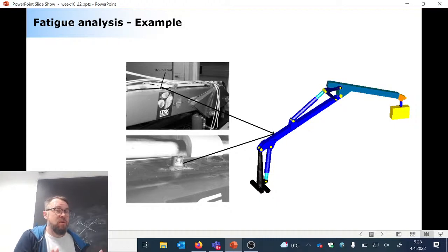And definitely you don't want to put anything that is more like decoration in a highly loaded area. And this is exactly how this design was made. Look at this, it's just to make sure that the pipes are connected. You can put this connection anywhere you want, but definitely you shouldn't put these connections in a location that is highly loaded.